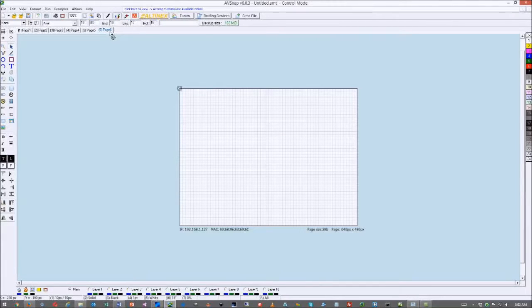The first page that I'd like to do, which is my last page typically, is going to be my template. I don't know what I'm going to do with the template, but I always have a template, and I click on it, set it as a template, and make it invisible. So that's my last page. The next page I'd like to do is what I call the TCP page. A TCP page allows me to test all my control codes through the network, so anything that I'm controlling.